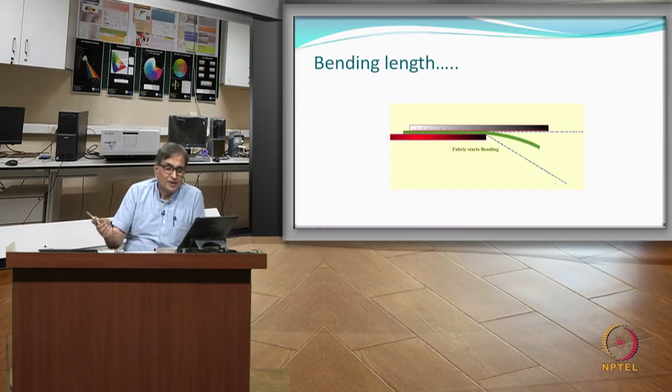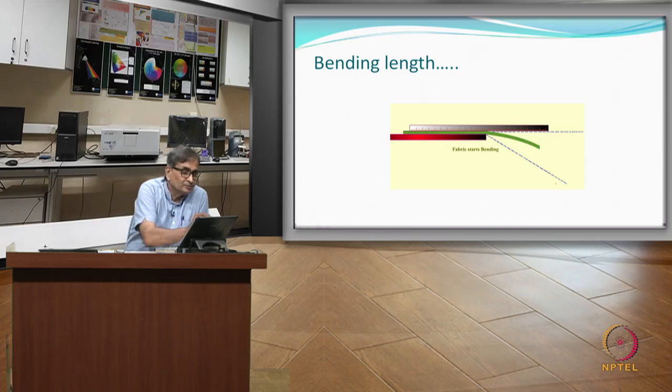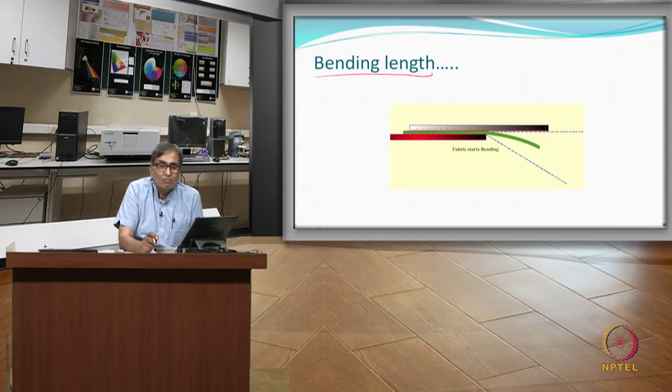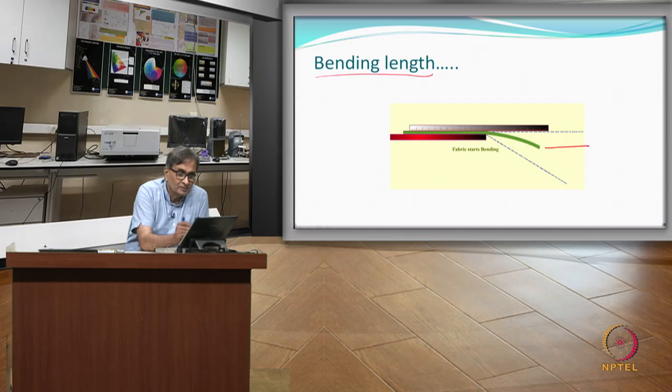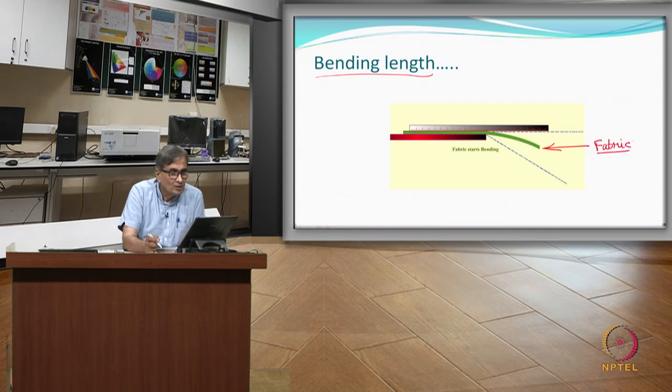One thing that can be tested is bending length. Bending length can be tested by taking a strip of fabric, again based on the standards. Let us say this is the fabric, and there is a scale.